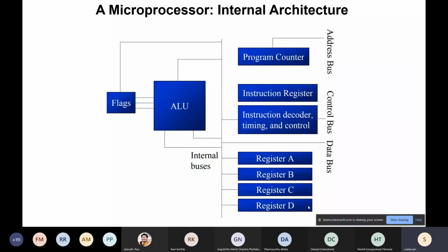After you power up, these registers may have garbage values, or they may have been initialized to a certain known value. Assuming register D is already known to be 00 hex, because it is an 8-bit register and the data bus is 8-bit. For simplicity, we can consider all registers 8-bit, and the instruction register 8-bit. The program counter is 16 bits, because you have 16 address lines. After the second byte came and sat in the register, you have to do the addition of A and D.